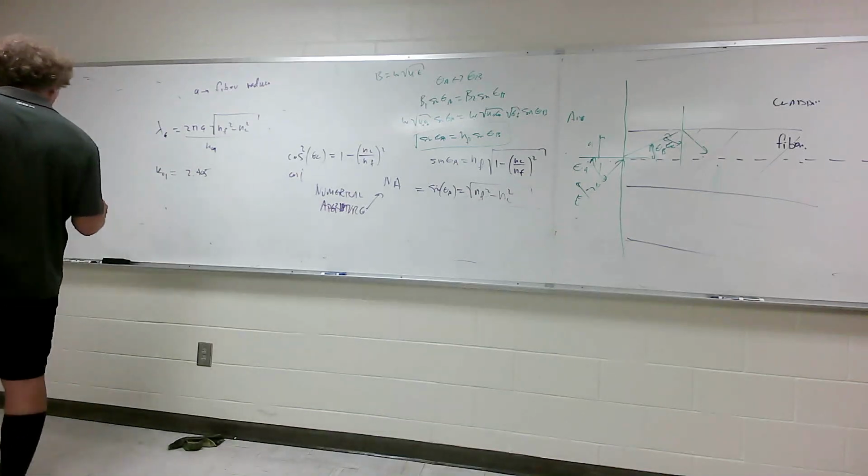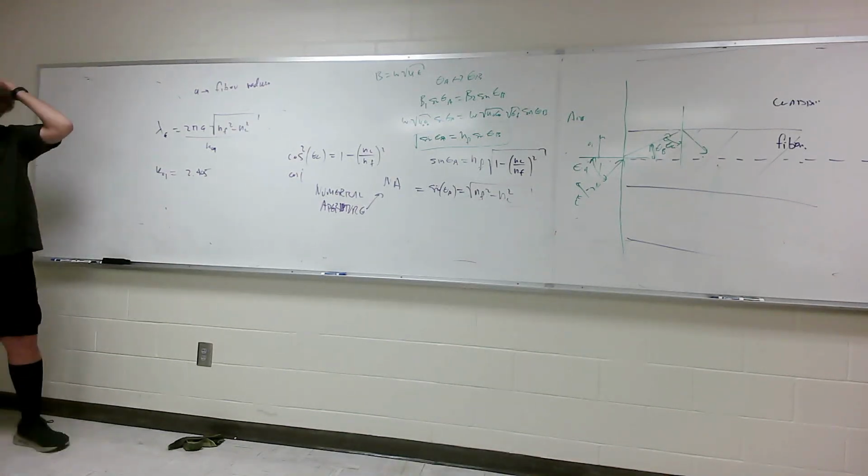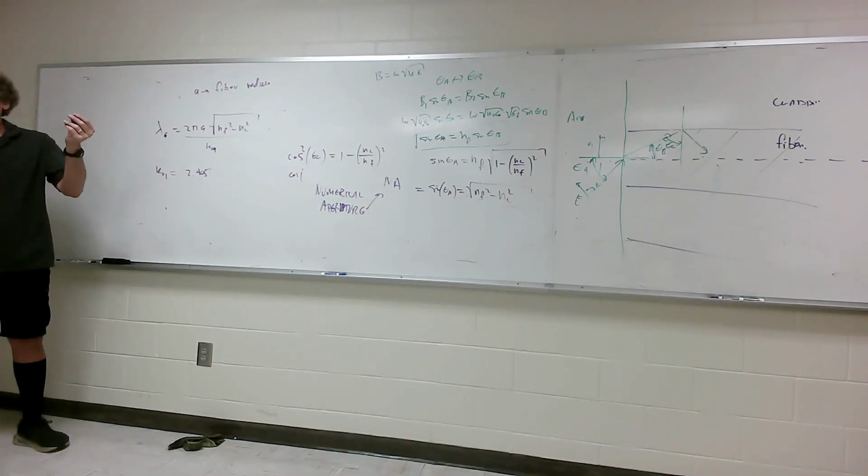If you were to go ahead and solve, you know how when we solved for the cutoff frequency for the P1 mode, remember when we got the expressions, we broke up the E field Ez and we got those sine of beta x times x, sine of beta y times y, e to the minus j beta z times z, do you all remember that? And we found out what? That beta x itself had to be equal to m pi over a, and beta y had to be n pi over b. Do you all remember this?